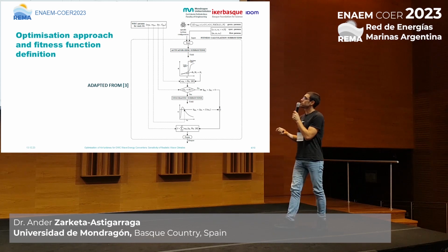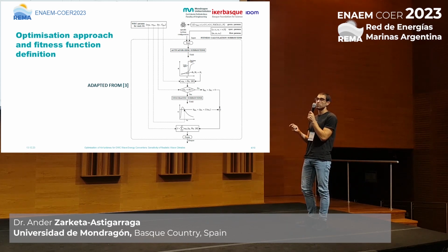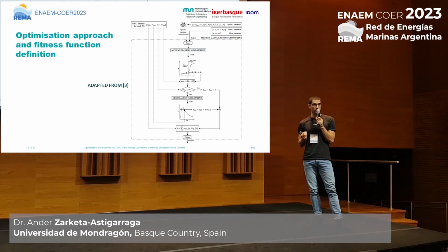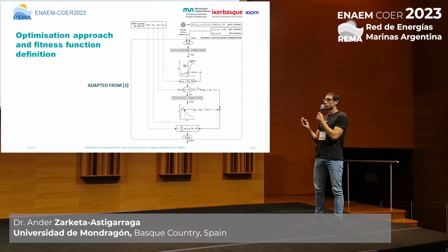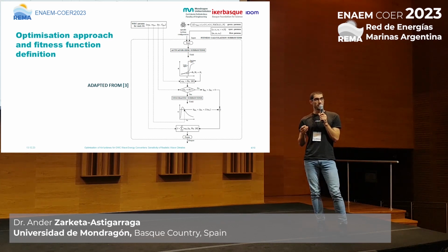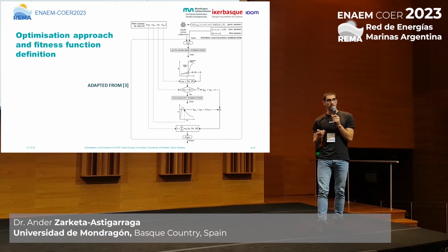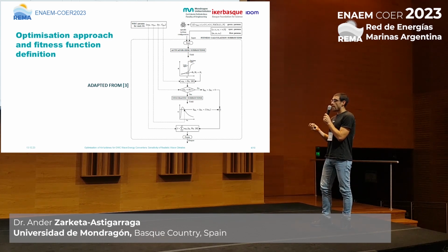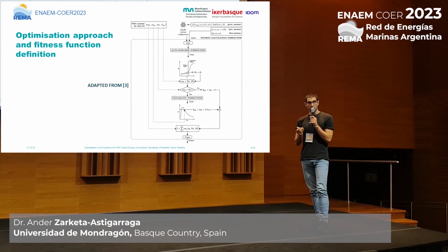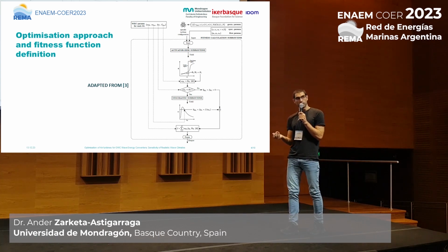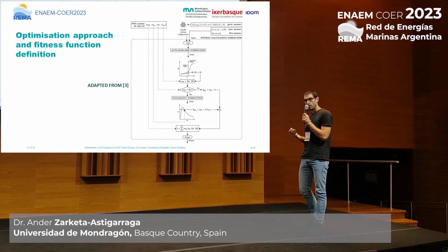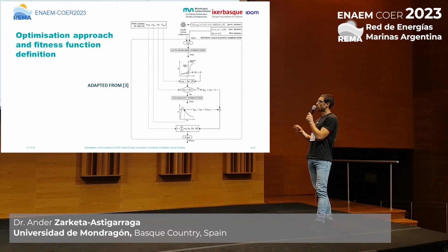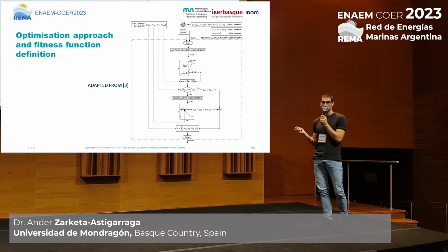And we have, as well, a pre-established interval of accepted rotational speeds. Now, that's not just for safety issues, it's also for avoiding compressibility effects on the semi-analytical code, okay? Now, if it happens that the rotational speed we are calculating falls outside the pre-established interval, we set the efficiency for such a C state to 0.